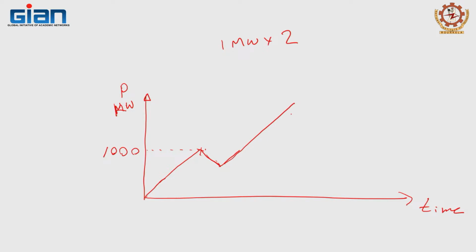And if there is still more water, we will take the first machine also to full load. Let us assume this is 800, so this may be 1800, and then you start the second machine also, and take the first machine another 200 to make it 2000. So likewise in operation, depending upon the type of turbines you have, you have to optimize how you load and unload them.